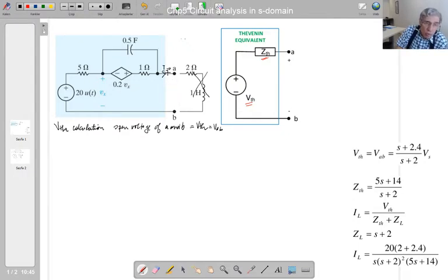So open circuit means that current is equal to 0. What does this mean? So that current is the summation. So let's choose references for these two. So that current here is the summation of those two currents. If we write the Kirchhoff current law equation for this node, summation of those two currents is equal also to this resistor current.